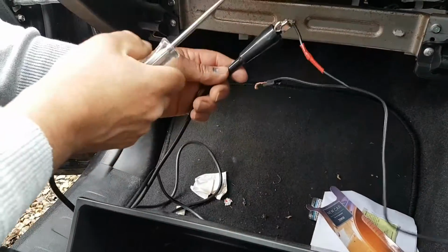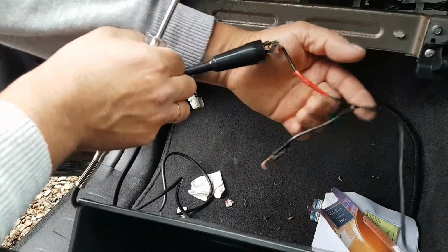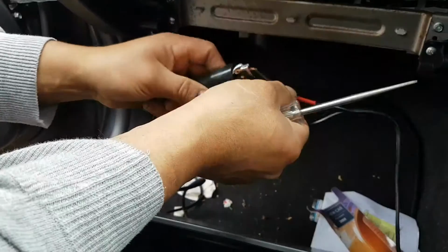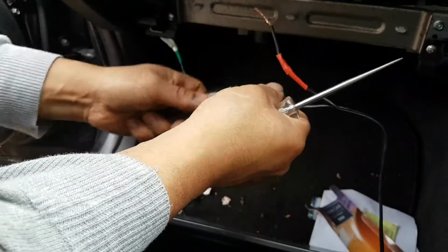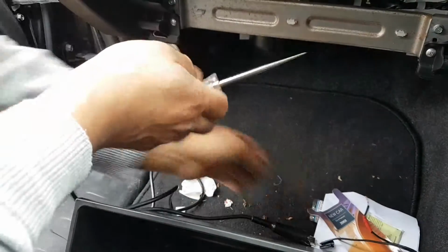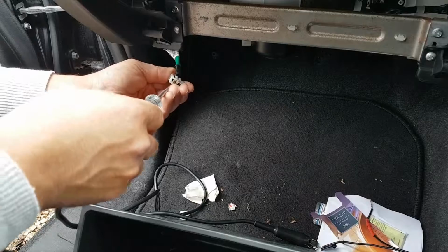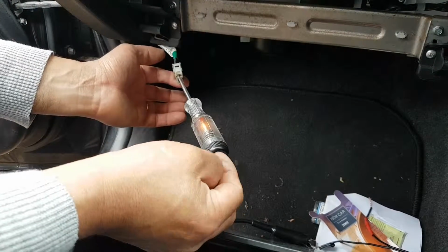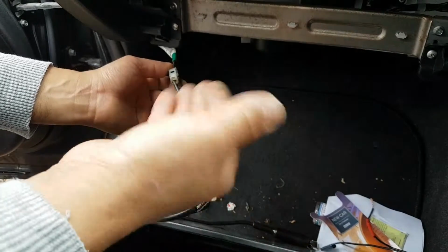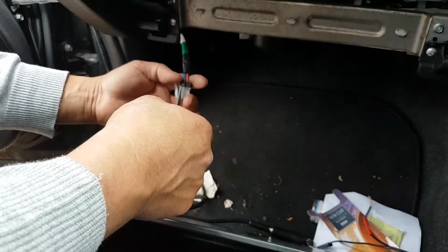So right now I'm getting this wire here. It's coming from the cigarette lighter. So this is my positive, this is my ground, and what I'm going to show you is, if I put the test light here on the ground and I go here on my blue and white, as you can see I have ground. Okay, I'm not really loading the circuit yet, but at least it shows me that I have ground here. We might have a ground issue, we'll check later.